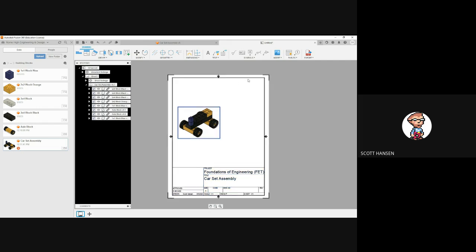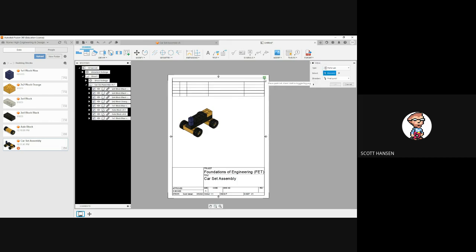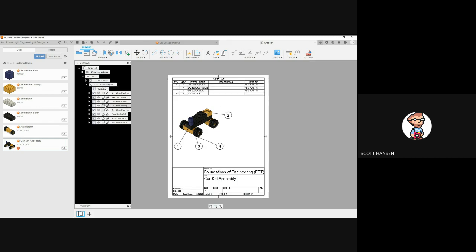All right. Typically, with an assembly view, we have a parts list, and we've gone through and labeled all our parts as we put this thing together. So it's actually pretty easy to create that parts list. Let me go up to Tables, and under the Table option, there is an option here for a parts list, and that creates a list of parts in this design based on the assembly that I've already done. All you got to do is click to place that parts list. Now, one thing you'll notice, it creates these little call outs for the different parts, makes it easy to see what those parts are. You might want to drag things around just to position stuff a little more so it's more easily readable.